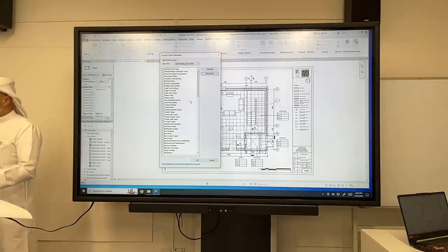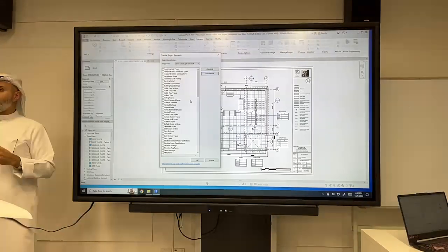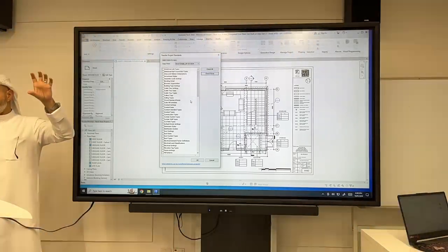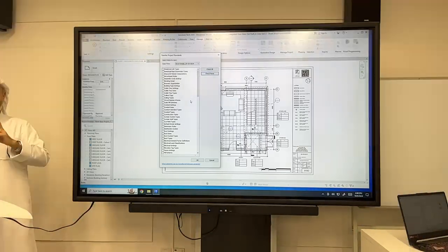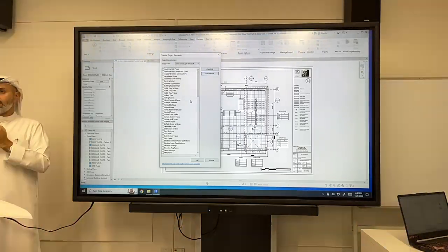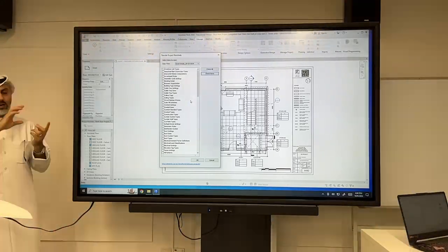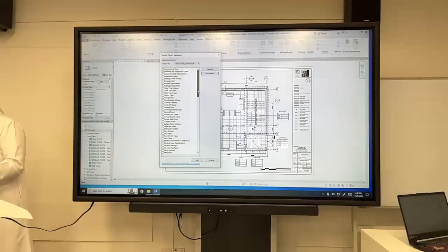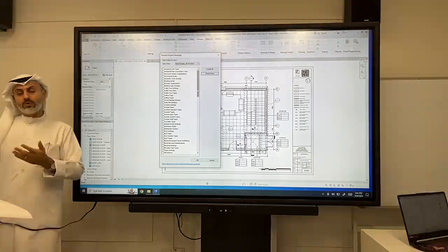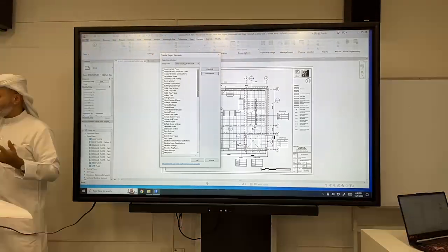Now, what we're trying to do here is transfer information and details and properties from one file to another file. Okay? What I did was two things. I had new walls and new floors and new hatches in this new file that now we're going to select to transfer. But generally, this is how you transfer things. So I want you to learn how to transfer items from file to file. Maybe you're updating things as you go along, but you don't have to start from scratch. You just copy the standards to the other file.